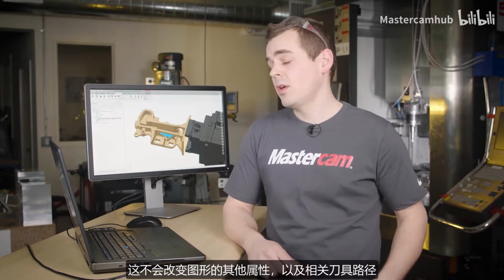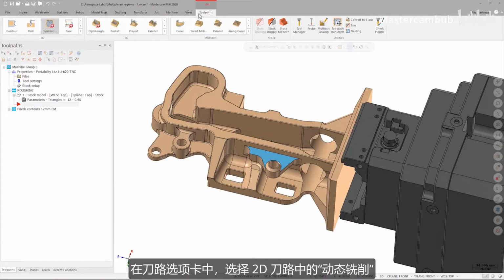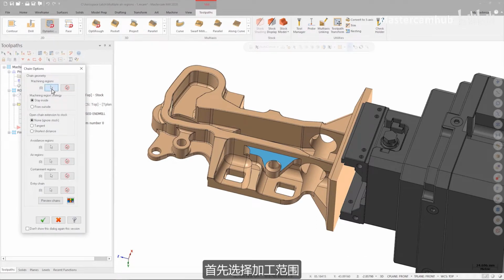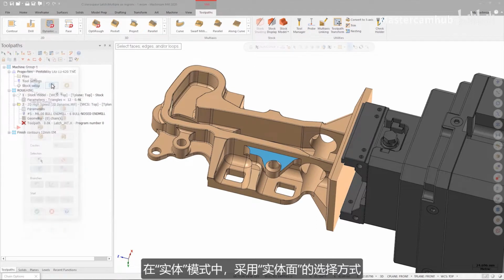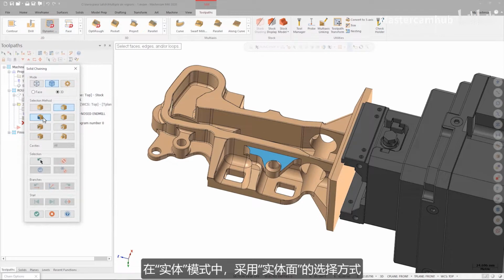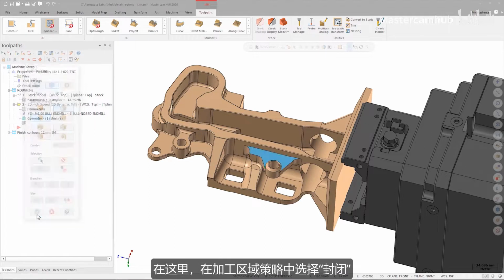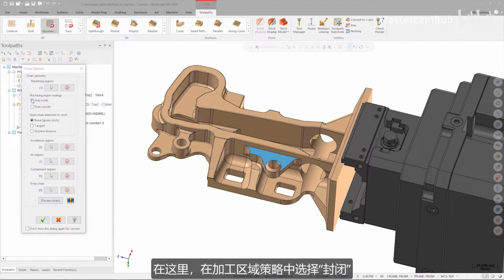Other than the color of this face, this makes no changes to the geometry itself or how I'm going to toolpath the part. On the Toolpaths tab, I select Dynamic Mill from the 2D toolpaths. I want to pick the machining region first, so I make sure I'm in solid selection mode, and I choose Face as the method. Then I select the face that we highlighted earlier. For this operation, I'm going to use the Stay Inside strategy.